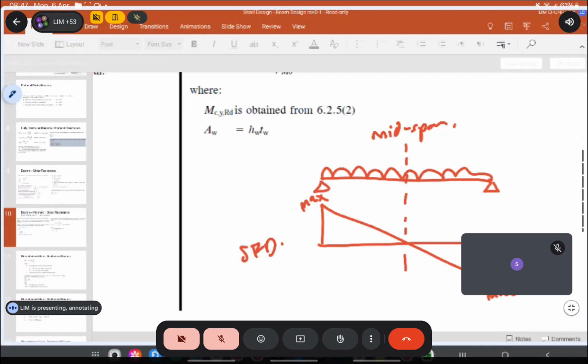Next, we look at the bending moment diagram. Your bending moment diagram is a parabolic shape for a UDL. Where is the maximum? Middle of the beam. So that's the situation we have. For shear force, it's highest at the ends of the beam. Bending moment is highest in the middle of the beam. So actually, my point is, they don't act together.